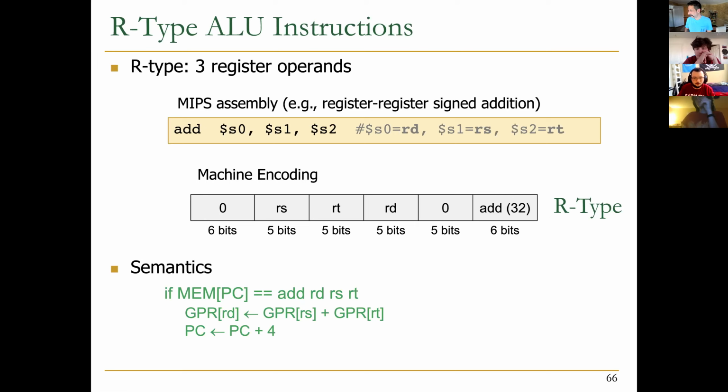I have a question. Yeah, go ahead. So at the bottom, PC to PC plus 4, what is the significance of adding 4? Meaning that the PC should move to the next instruction. You remember this had two parts. Beside executing the current instruction that is pointed by PC before incrementing it, PC every time points to the instruction that the machine should execute. So you should at the same time execute this instruction and also increment the PC, so next time you execute the next instruction in the code.